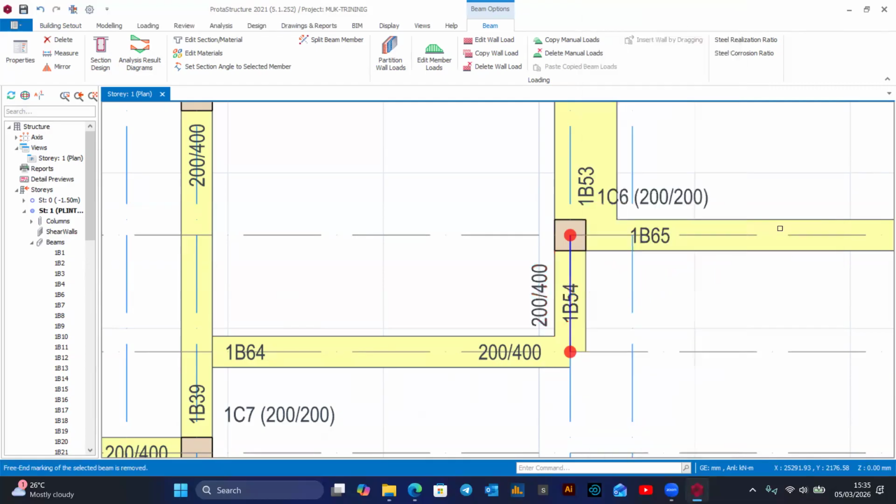If it is this option, then it will cease to be a cantilever. And this means that at this point, this beam is supported. Okay, but in actual sense, we don't have a support here. So the program will try to identify for you those conditions. But where I find that it is not right, you can use that option of marking with both ends supported.